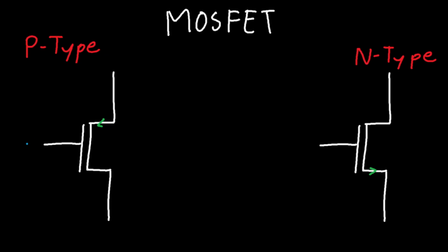All right. So what does a logic 0 stand for? Logic 0 just stands for 0 volts, or very low voltage, matter of fact. So let's say, hypothetically, 0 volts, all right? Right here, a logic 0 stands for 0 volts. Easy to remember, right? Well, if you have 0 volts going into this input, into the transistor, then this P-type transistor will act as a closed switch.